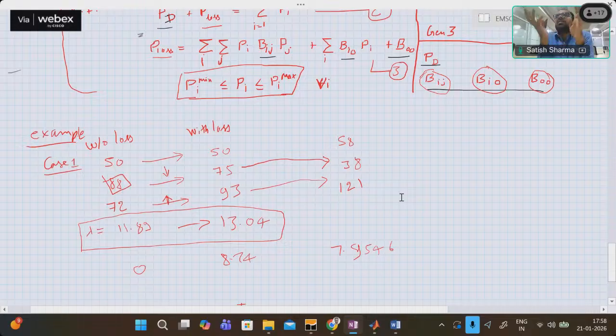Let's say in the daytime, as Professor Bhakkar also explained on the very first day, we have a lot of solar potential. But what happens if a solar plant decides to not inject anything? For that, a system operator has to keep a reserve. So one generator is basically there to supply that. Whoever is deviating from that dispatch should face some penalty.